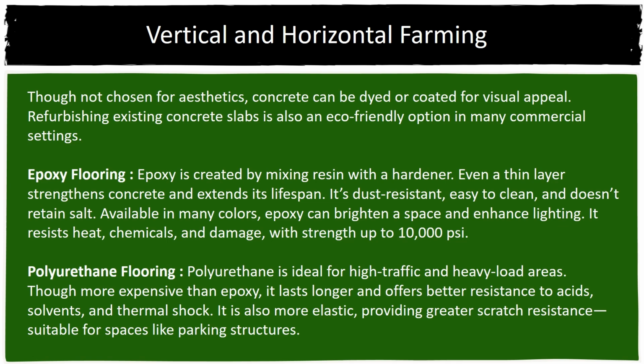Polyurethane flooring. Polyurethane is ideal for high-traffic and heavy-load areas. Though more expensive than epoxy, it lasts longer and offers better resistance to acids, solvents, and thermal shock. It is also more elastic, providing greater scratch resistance, suitable for spaces like parking structures.